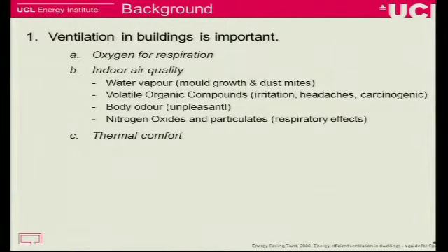People often think it's to provide oxygen for respiration so we can all breathe, but in reality that's a very tiny proportion. So in reality there's two main reasons for ventilation. The first off is to provide a good indoor air quality by diluting the pollutants that are produced inside buildings. In a domestic scenario, these are normally water vapor from cooking, cleaning, washing, etc. VOCs, the chemicals from new carpets, paints, things like that. Body odor from yourself or maybe your pets, which just isn't very nice. And the last one is nitrogen oxides, which are released from cooking quite often. And most of these have been linked to health impacts on the occupants.